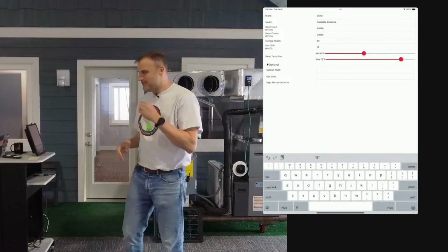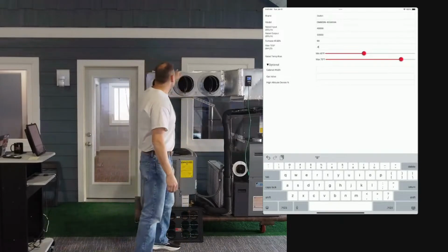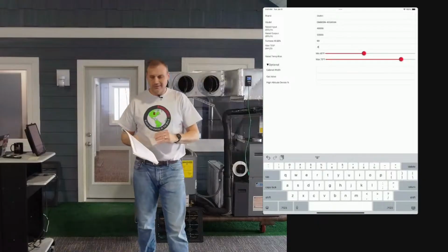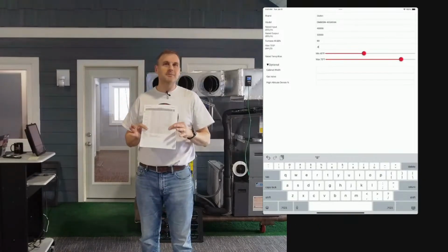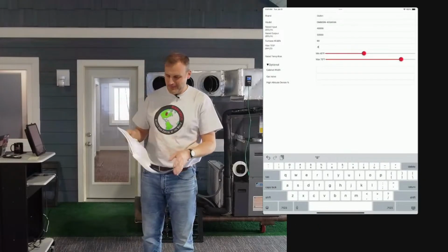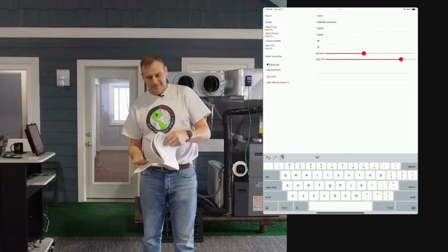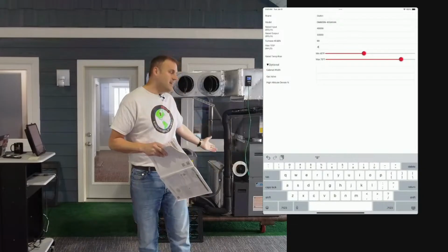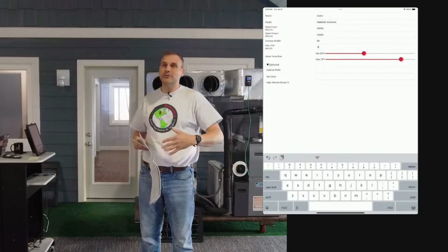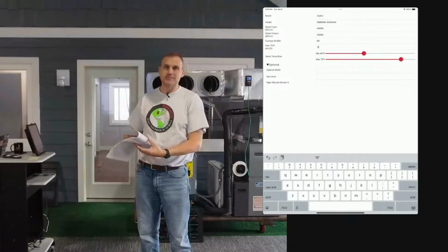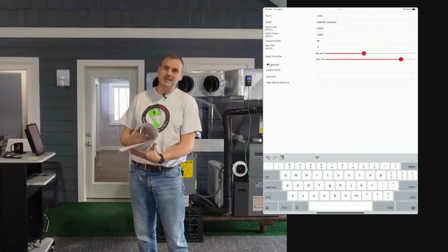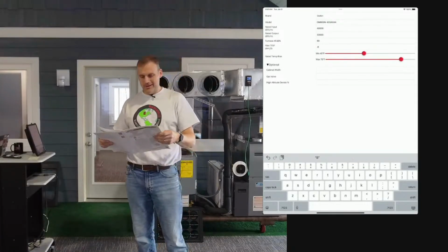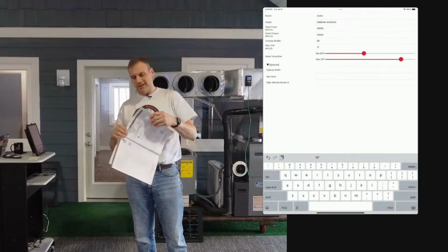So where do we get that static pressure measurement from? I just so happen to have right here the manual for the furnace behind me. The tag has 0.5 and it alludes to rated. There's a big confusion between rated and max TESP. In this manual, it says heating mode speed selection.